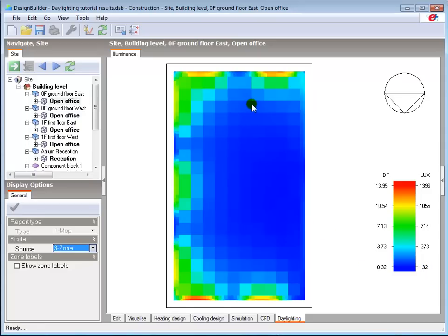You can clearly see the grid, with the 1 meter maximum grid squares in the majority of the zone and the 0.1 meter minimum grid squares used at the perimeters, where the 1 meter grid won't fit. The 0.5 meter perimeter margin is also clearly visible as the border between the daylight grid and the black line representing the zone boundary.